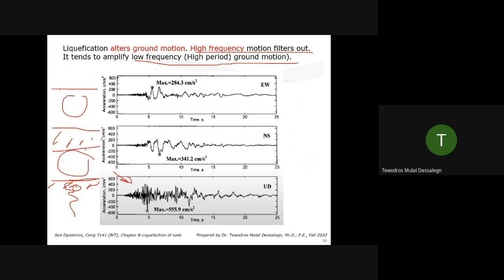But in the meantime, let's say the wave is propagating properly up to a certain state. Let's say it depends on the state. In this case, it looks like it liquefied pretty much right away. Then you see some kind of wave propagation. Then all of a sudden you see high frequencies filtered out. Only we see the peak. Just by looking at the ground motion, you can say if liquefaction occurred.